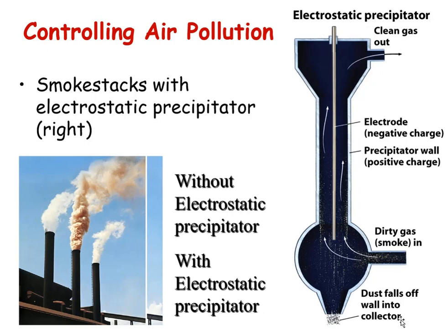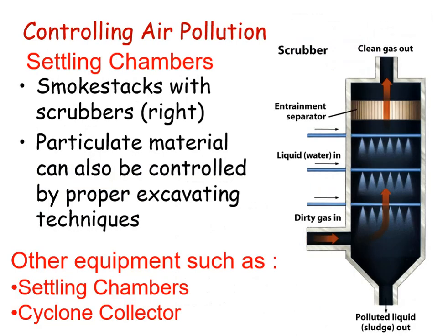So these precipitators can collect the dust particles and some of the gases also. It will not allow the harmful particles to go outside into the environment. So it can be collected, right? Like here, the gas is containing a lot of solid particles. So if you provide the electrostatic precipitator having the charges, it will attract all the solid particles. You can collect this as dust from here, and the clean air will go out. So these are the things which you can provide in the industries to control the discharge.